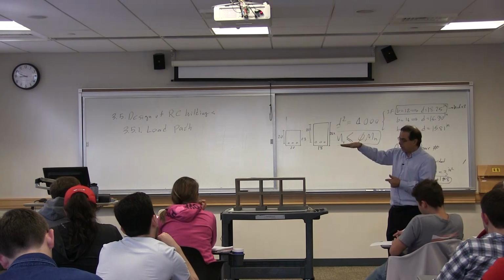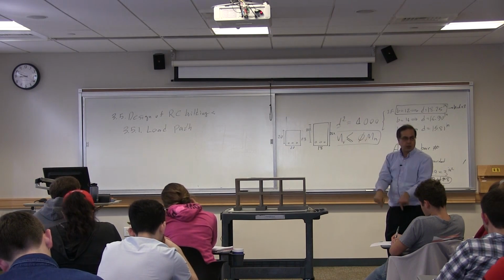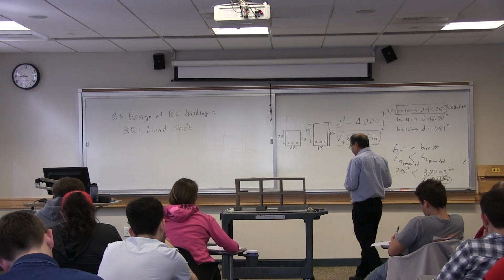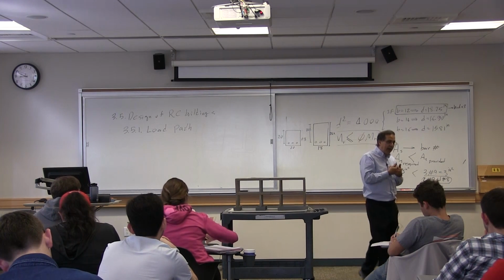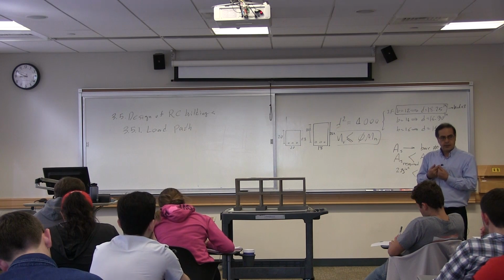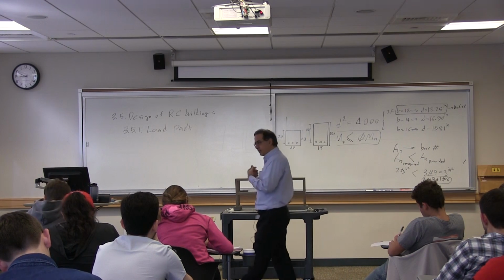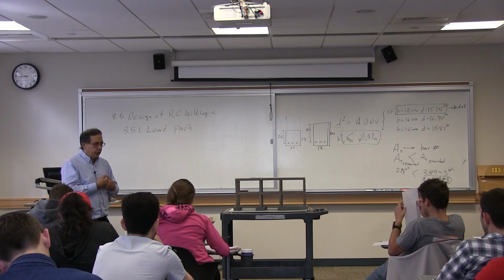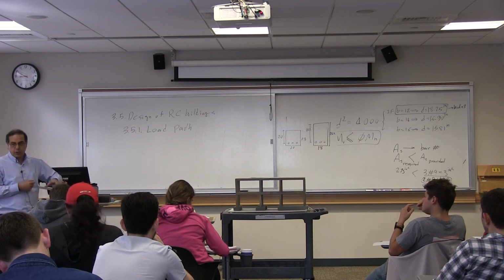Load path is, under gravity load, from the slab to the beams, from beams to the columns, from the columns to the footing. This is called a complete load path. You need to understand the load path in order to model your structure. As I mentioned last time, structural modeling is the most technical part of structural engineering. In order to model the structure, you need to know how the loads are transferred.